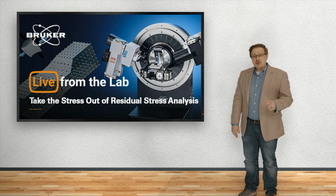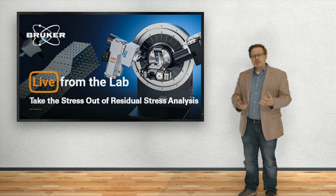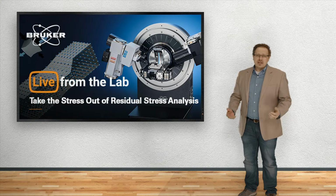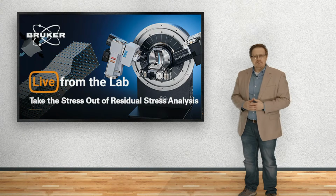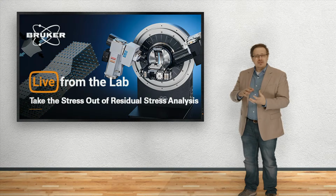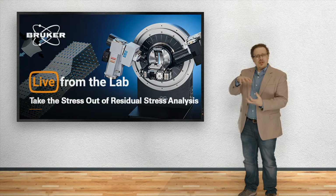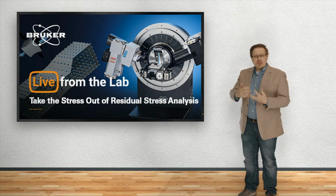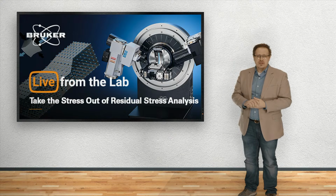Now in today's episode, we're going to talk about residual stress. When you take a material and you apply a load, that load is the stress, and its natural response is to stretch a little bit, or create what's called a strain. In the beginning, when you first start applying that load, there's typically a linear relationship. That is, we're just squishing the atoms a little bit or pulling them out a little bit. That response is completely reversible. If you remove the load, it's going to go right back to its original state.